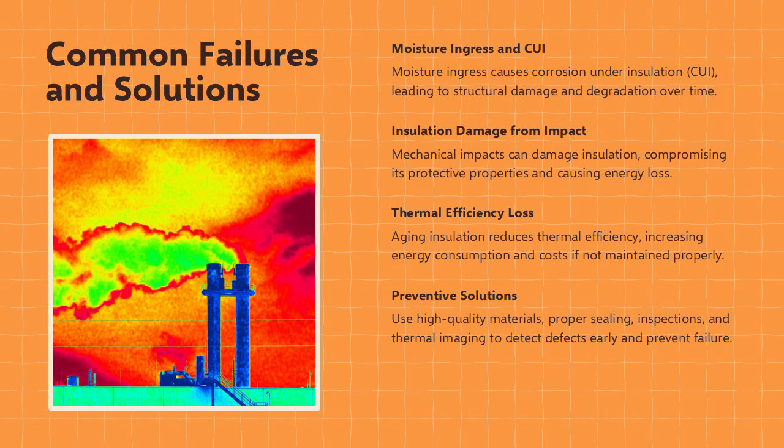Common failures include moisture ingress leading to CUI, insulation damage from mechanical impact, and loss of thermal efficiency due to aging. Solutions involve using high-quality materials, proper sealing, and implementing inspection programs. Advanced techniques like thermal imaging can detect insulation defects early.